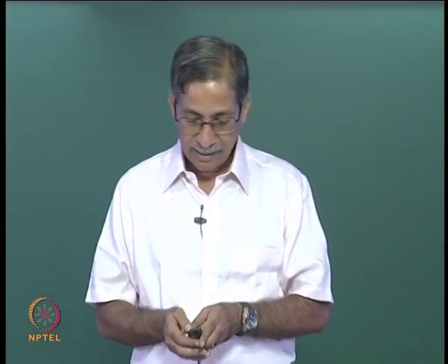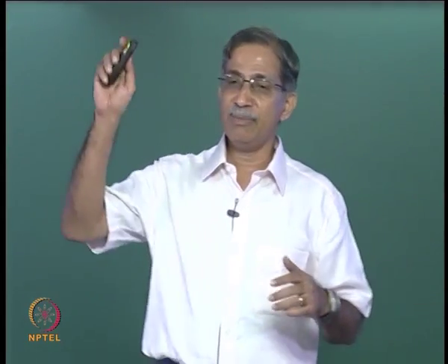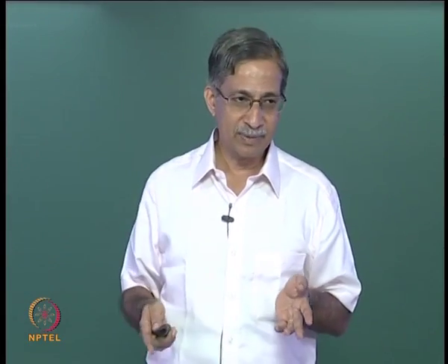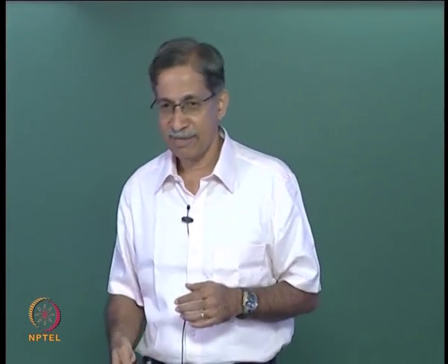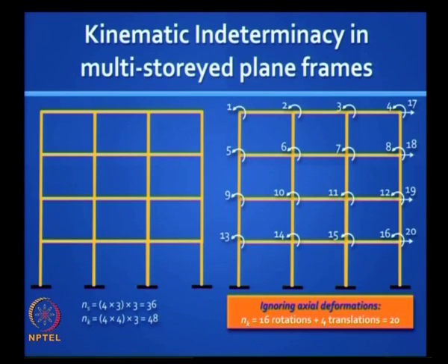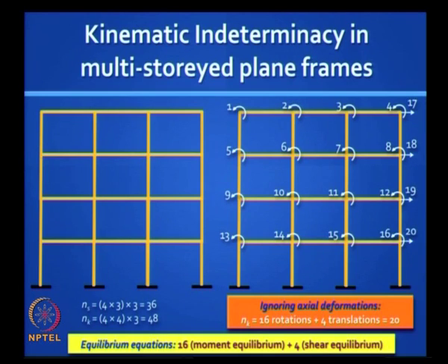Okay? And there are serviceability limitations in a tall building. The maximum drift in the building should be limited. Usually it is height by 500 under lateral loads. So, can you analyze a frame like this? Exact solution? Yes, that is the idea. We want to be able to handle any structure, any skeletal structure of any shape subject to any loading, including indirect loading. That is the objective of structural analysis.